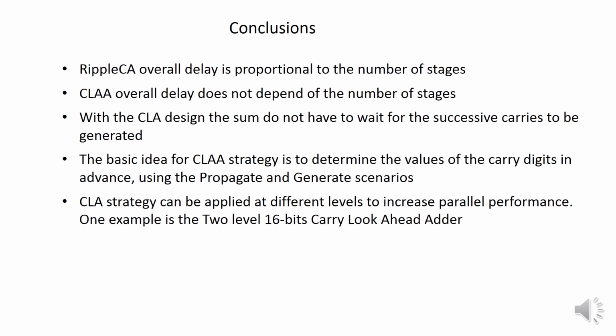The basic idea for the carry look ahead strategy is to determine the values of the carry digits in advance using the propagate and generate scenarios. And finally, the carry look ahead strategy can be applied at different levels to increase parallel performance. One example is the two-level 16-bit carry look ahead adder that we have just seen.